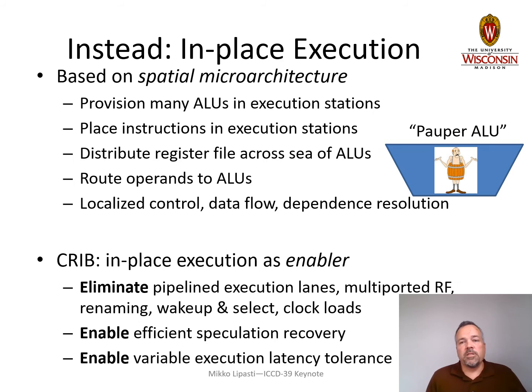So rather than building machines this way, maybe we should build machines with more of a pauper ALU approach, where we have ALUs sitting there begging for work to do, right? Give me something to do because I'm just sitting here idle. So let's provision as many ALUs as we can afford in a spatial structure. Let's place instructions into these execution stations. Let's distribute our register file across this sea of arithmetic logic units.